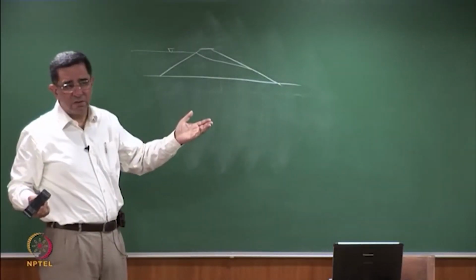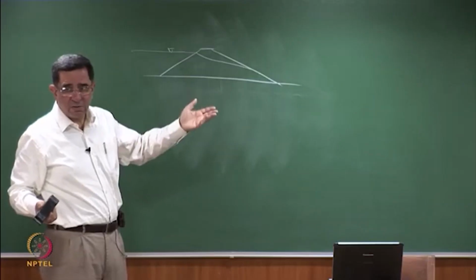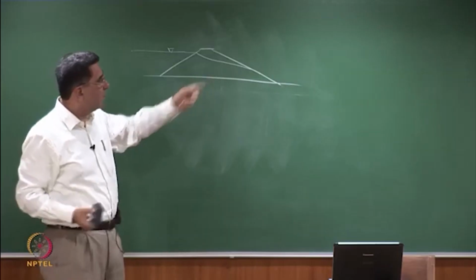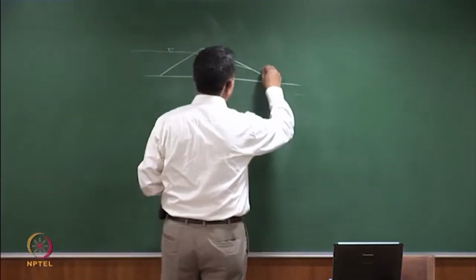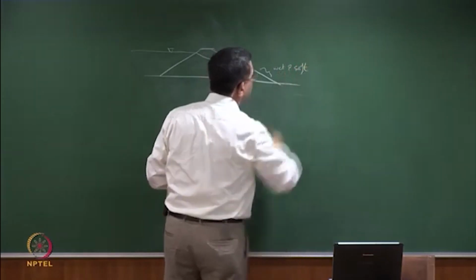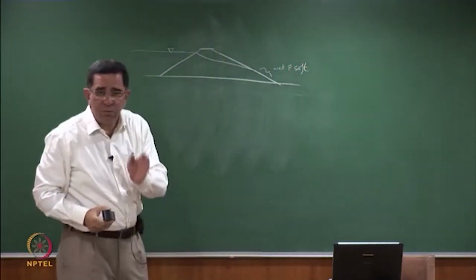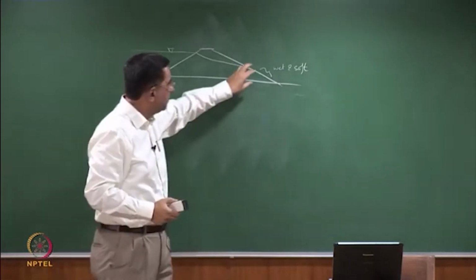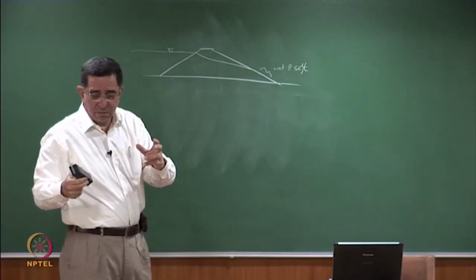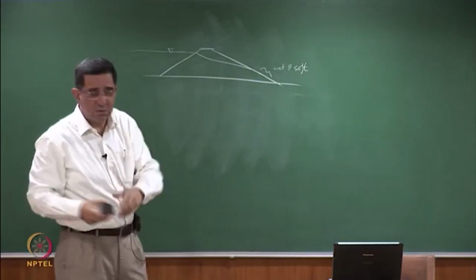You know all the ways of constructing this. There's the Casagrande method. You make a flow net. You can calculate the seepage. This is not a good way of designing an embankment because this will remain wet and soft. And eventually, you'll have piping. So you build in some elements so that this doesn't happen. And that's the entire philosophy of design of a homogeneous embankment.